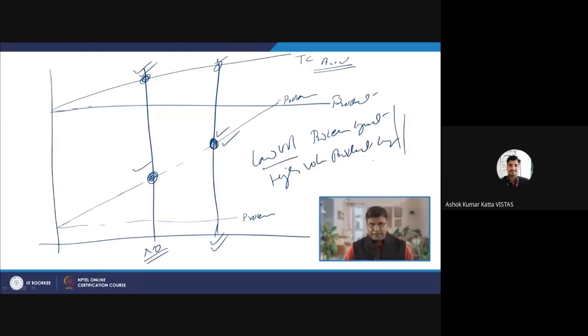Now, here I will summarize this presentation. In this presentation, basically I have talked about the three types of layouts and their features, like the product layout, the combination layout and the fixed layout. The product layout is suitable for high volume production and limited variety products, while process layout is suitable for limited volume and high variety products. Thank you for your attention.